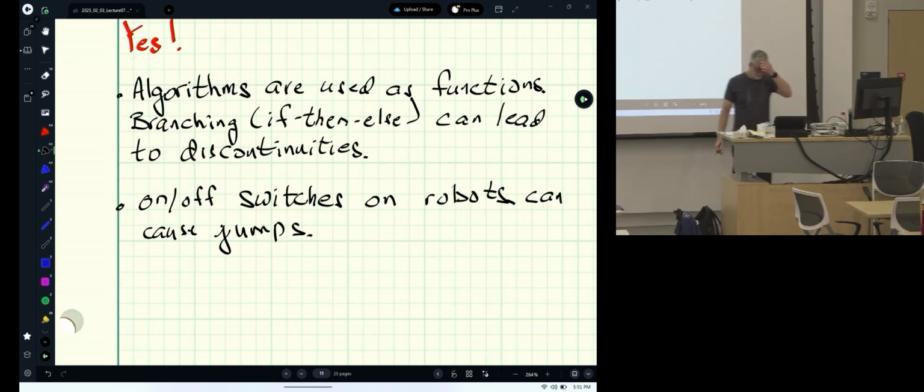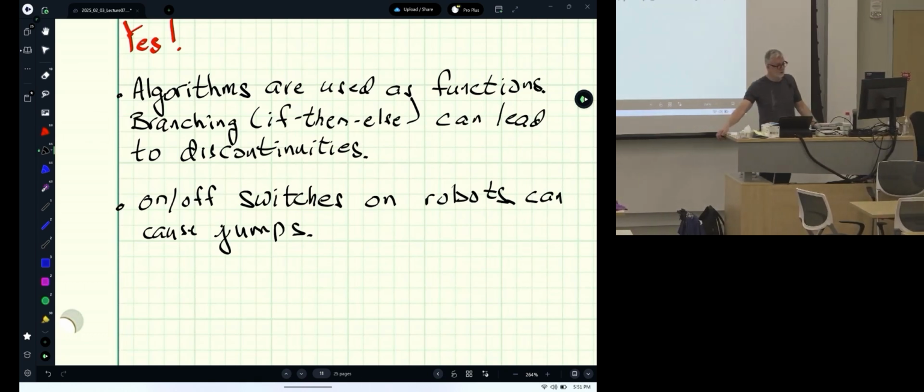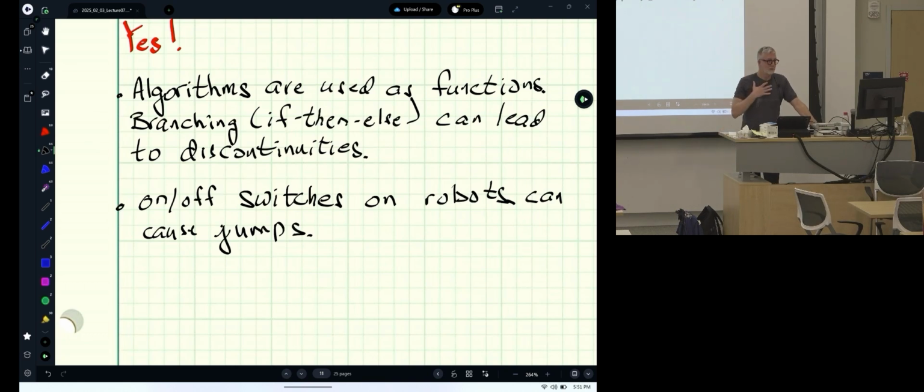So here's things that young students working in a lab, whether you're a grad student or an undergrad, happens in my lab with the Cassie robot. One of the students asked them to go over and turn on the robot, okay? Powers it up. Now, what if the person who wrote the control laws on it didn't say when the robot is first turned on, keep the motor torque at 0?